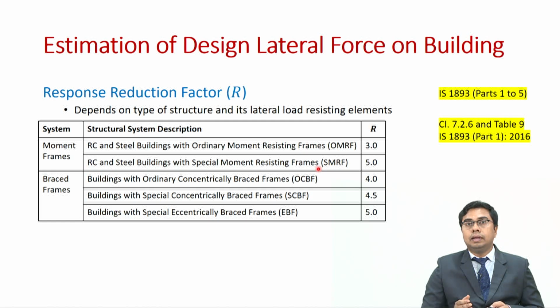If your moment frame satisfies the design conditions or guidelines mentioned in IS 456 for RC buildings and IS 800 for steel buildings, that moment frame will be classified as OMRF.